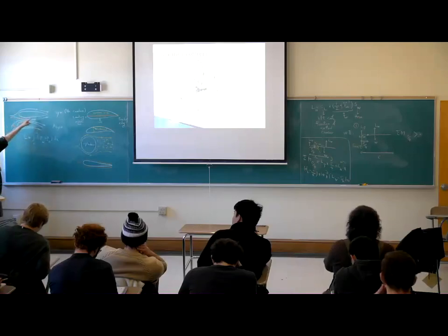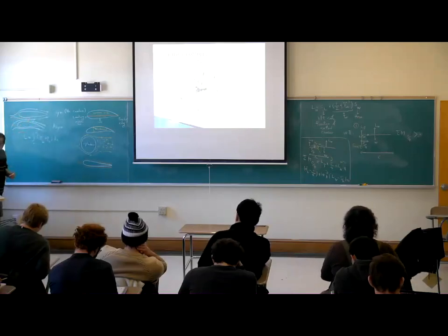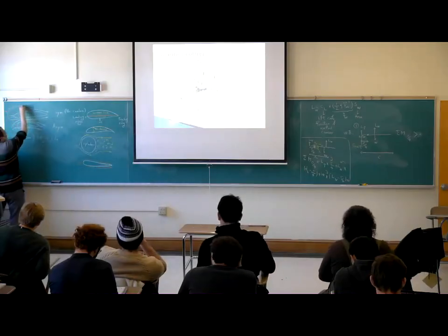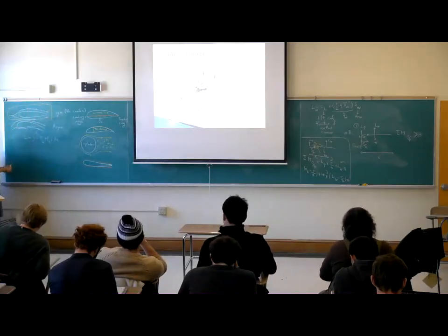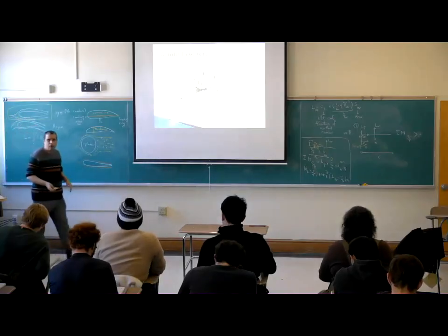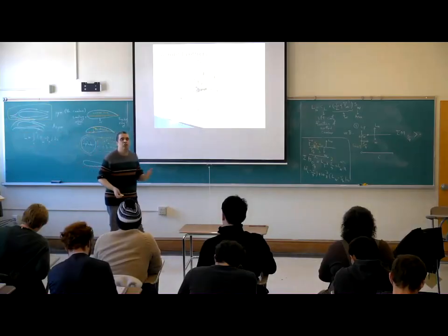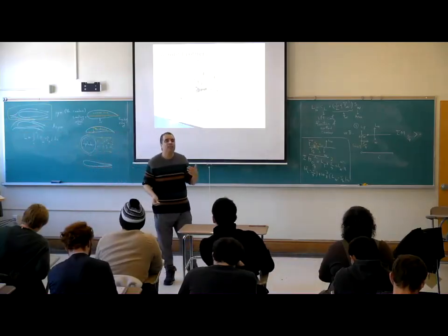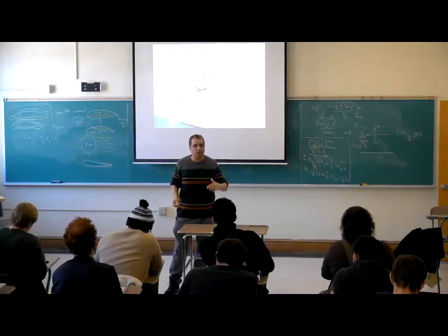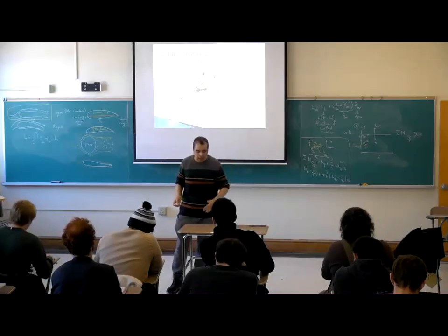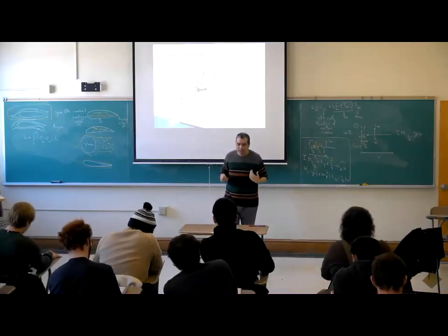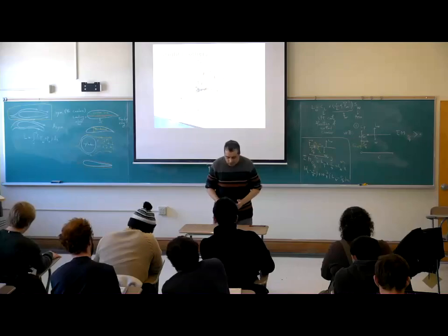Consider the first airfoil. The first airfoil is very symmetric. The flow doesn't have any priority to move faster on the top or faster on the bottom. Take a look at me. I am a fluid flow. I come here and then I divide.